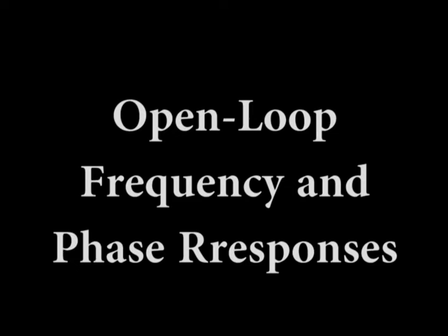Open loop frequency and phase responses. Open loop responses relate to an op amp with no external feedback. The frequency response indicates how the voltage gain changes with the frequency, and the phase response indicates how the phase shift between the input and the output signal changes with frequency. The open loop gain, like the beta of a transistor, varies greatly from one device to the next of the same type and cannot be depended upon to have a constant value.